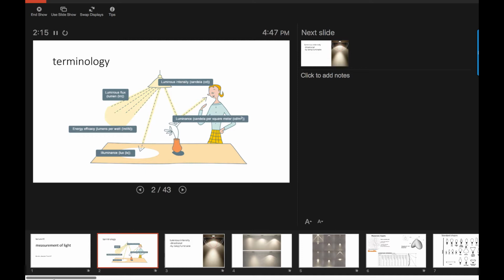Anyway, there's a number of other things that we have talked about, including illuminance. That's the measure of light landing on a surface, measured in lux or foot candles. Foot candles in the US, lux everywhere else on the planet. And you might hear in the book them talking about luminance, which is different than illuminance. That's basically the amount of light reflecting off of a surface. And you can try to use your phone as a light meter to determine luminance, reflected light, but it generally doesn't work particularly well. You can only get a broad sense. Illuminance, on the other hand, the phone works pretty well.